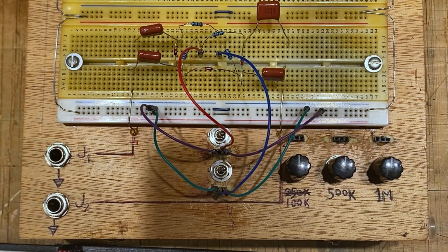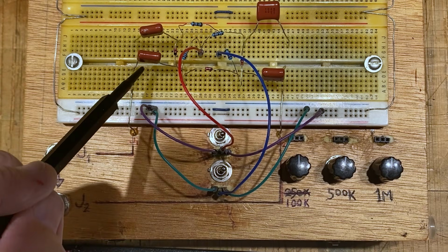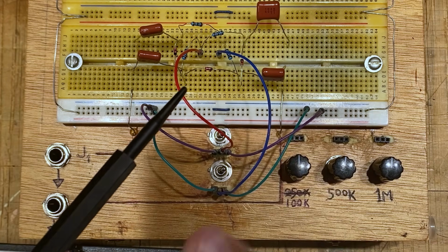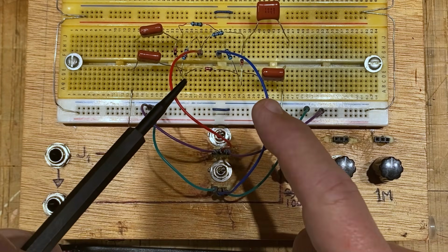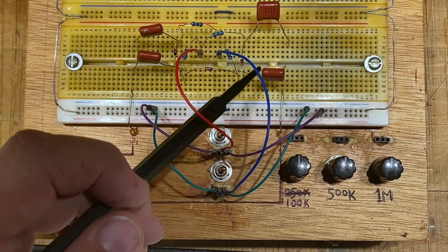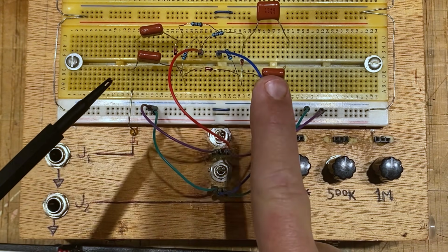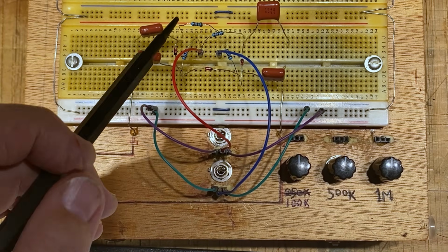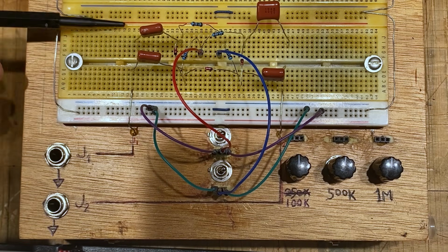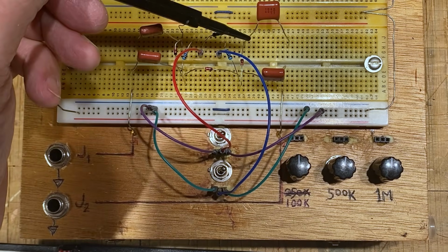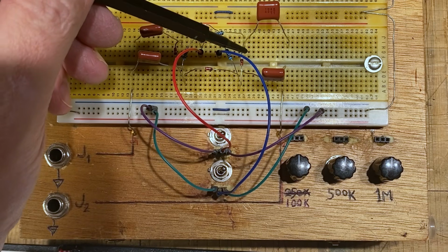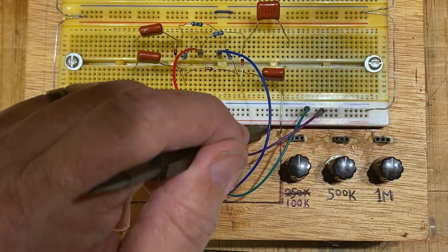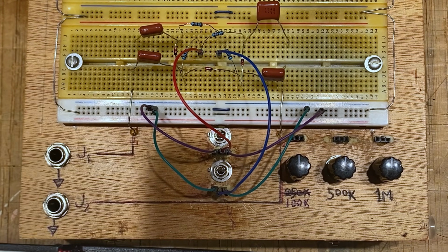Okay, so the way I have that set up, it will come in, and depending on the position of these two switches, this will either be high and low or low and high. If it's in high and low, this is going to pass through to the output. If it's low and high, this is reverse biased, so the signal will travel through this diode to the effects send. It will come back through. This diode is forward biased, so the signal will go through and then to the output. That should work.